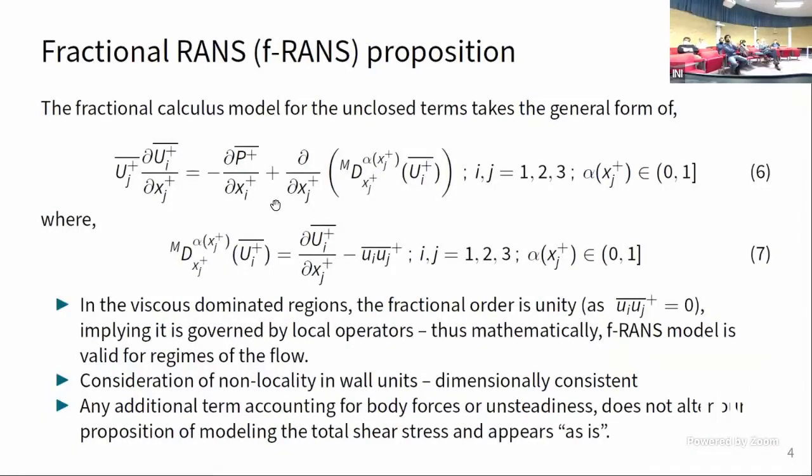In the next slide, I will talk about two such constructions. One thing I have to point out here is that the usual approach has been looking into modeling those little u_i and little u_j bar terms. That is what we call the Reynolds stress. But my proposition is that don't look at the Reynolds stress. Instead, model the whole stress term together with its local part.